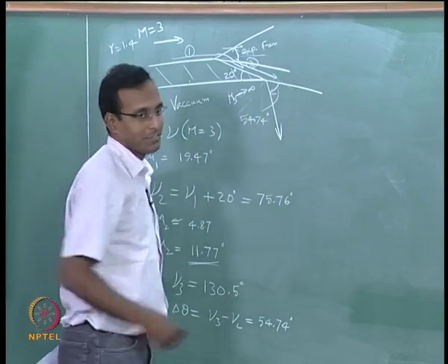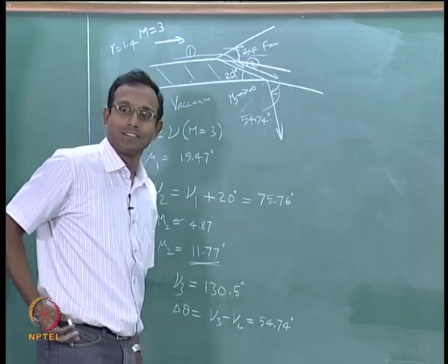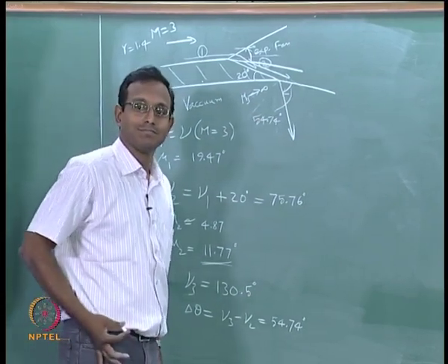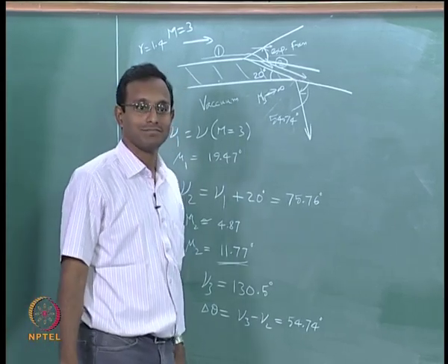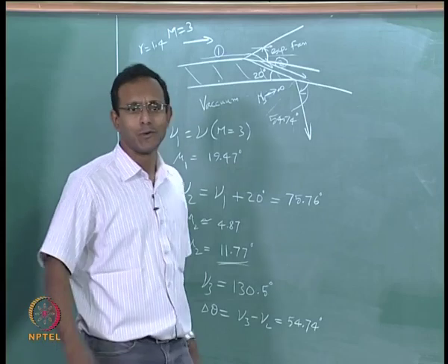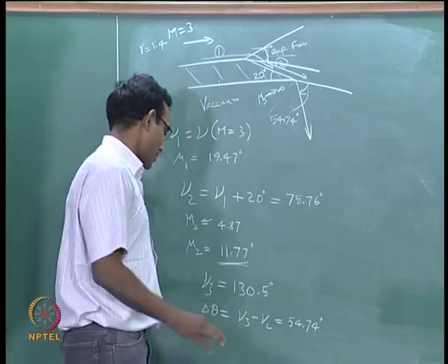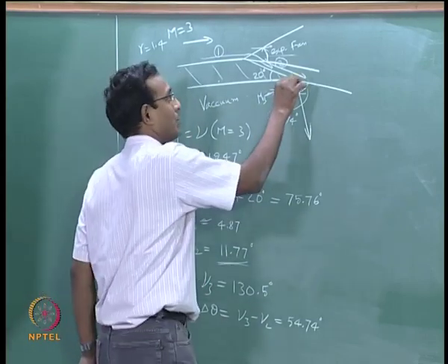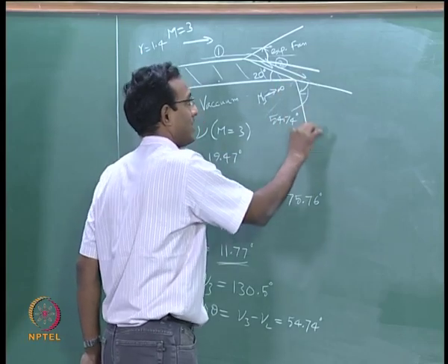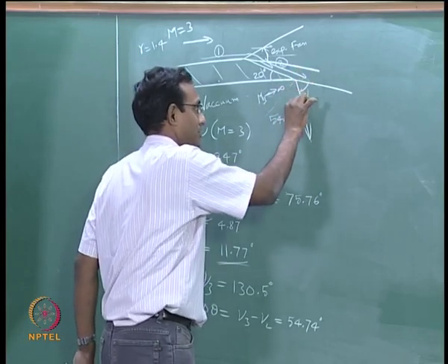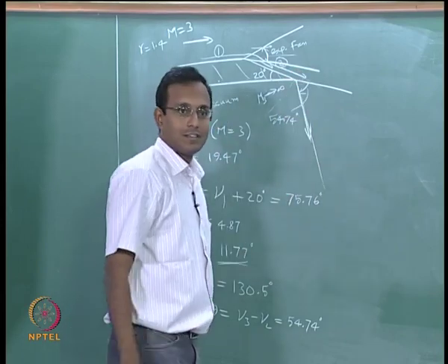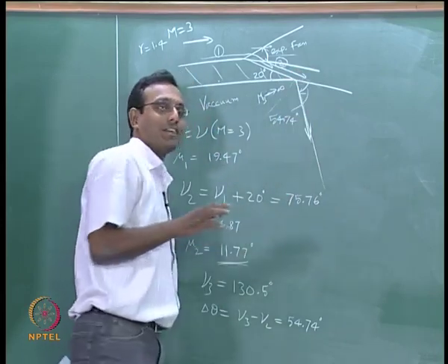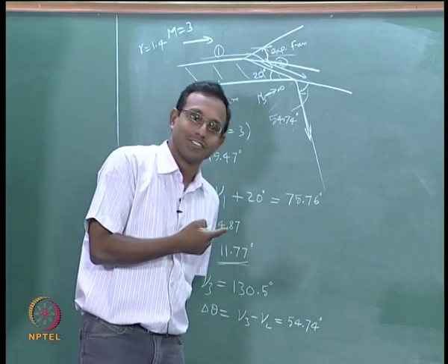And the last expansion wave, what is the mu value for that? Sin inverse 1 by infinity. Sin inverse 0 is 0. So you are going to have a mu angle 0 with respect to flow velocity vector direction. My last expansion wave is going almost on it. So it comes to a point where it is not physical for us.